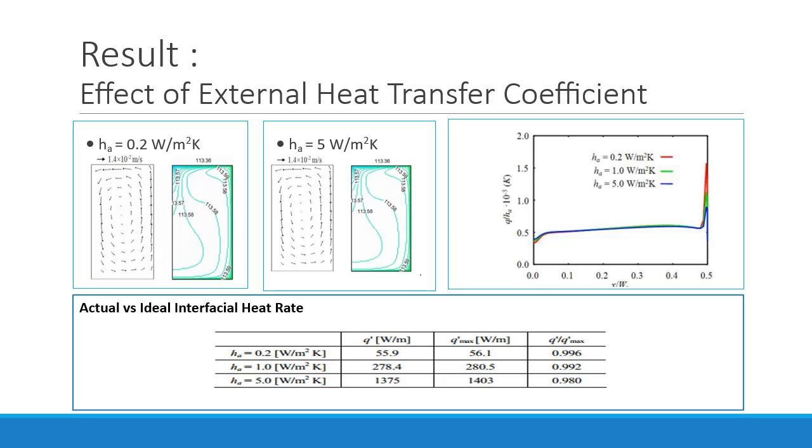My personal comment is I think it is necessary to explain how to manage the ambient air convection coefficient, since that cannot be obtained by direct measurement. The author shows us that the results between simulation and experiment are almost the same, about 99% accuracy on average. I just still wonder how to manage the ambient air in order to have a certain value exactly, which the result will be compared to the simulation result later. However, anyway, the results show us that the set parameters for simulation are valid because it has very similar results compared to the experimental one.